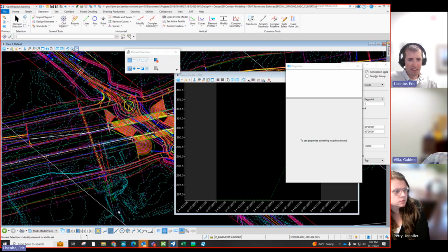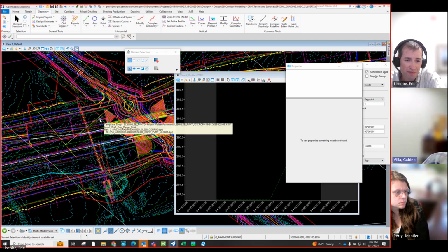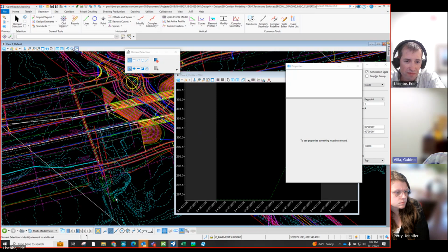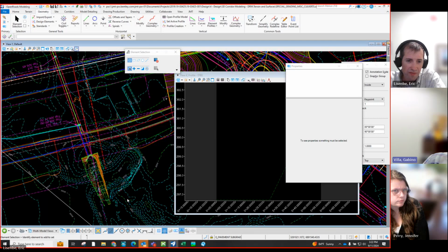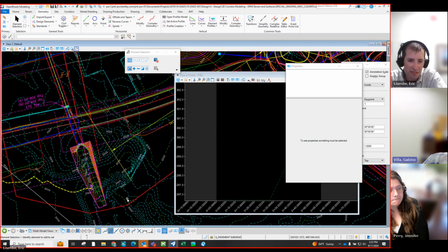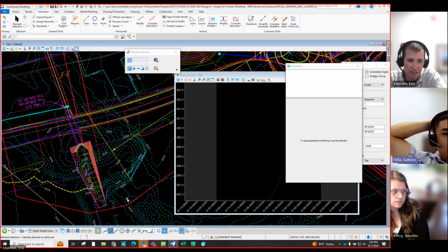Because I know, like right now, the way you create the terrain, I'm not going to do one for every culvert. It's mainly these ones with special grading. Maybe each side would be good, depending on how it gets created. Because when you do it by just the boundary or breaks, it works fine. But if you use the feature definition one and have two separate terrains in the same DGN, it starts trying to solve together and does triangles in between.